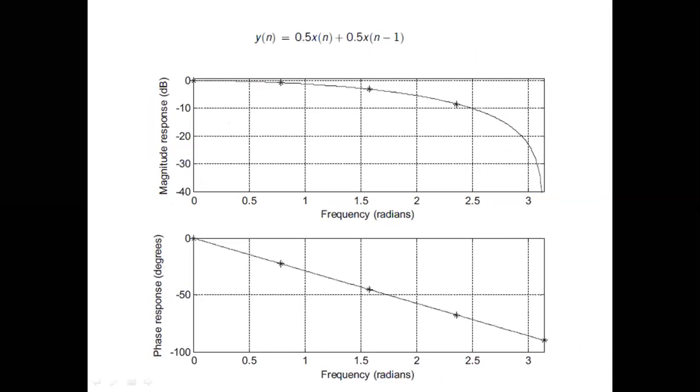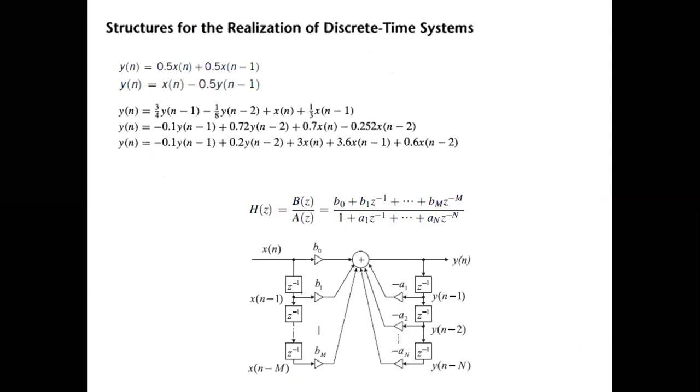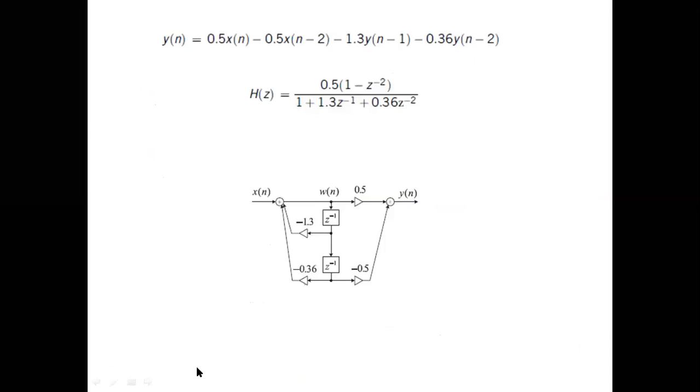Higher the filter order, more number of D flip-flops. Let me take a better example, this is a generalization. See here, this is a filter referring to n minus 2. If I have a second order FIR filter, it will have 1 D flip-flop, then afterwards 1 more D flip-flop, and in between there will be some combinational circuitry, and then you will have your output coming.